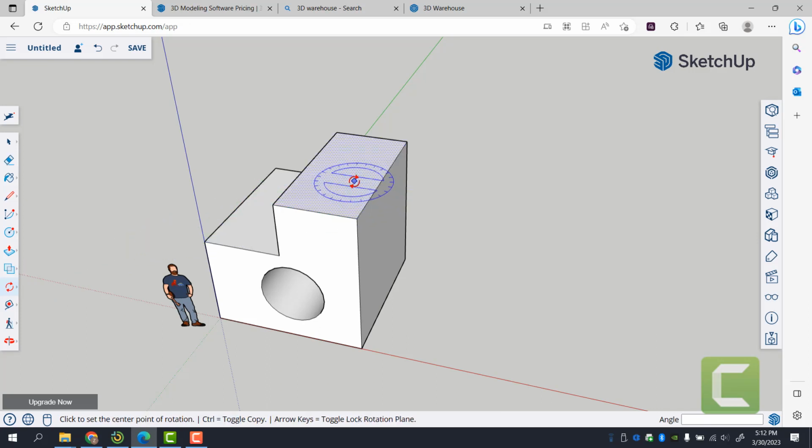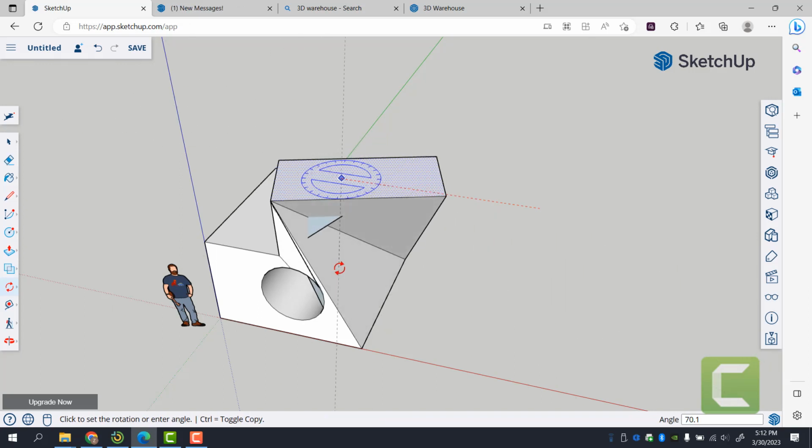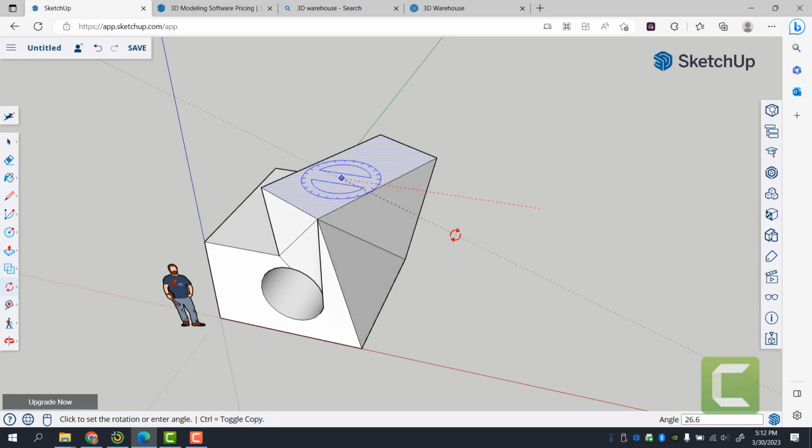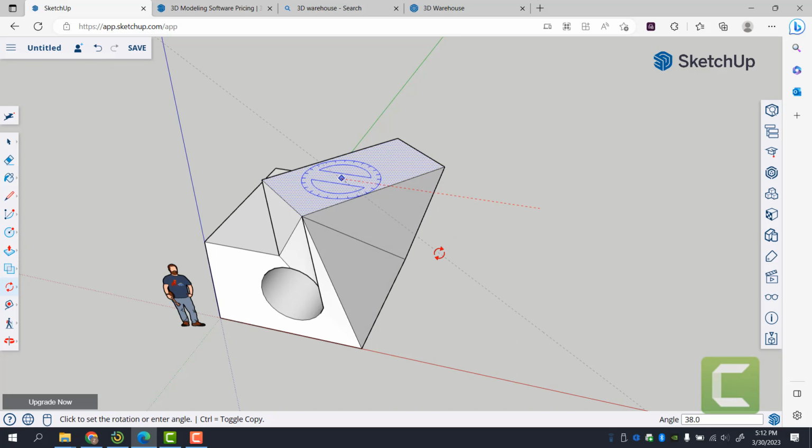And in the rotate tool, notice how I'm on the blue axis, which means there's a line going through that point on blue axis for reference of rotation or axis of rotation. And I am going to rotate about this red axis and turn towards green. Since I have not selected the whole object, it's just turning that surface. Again, very easy to visualize how it's turning just that surface and trying to maintain the bottom base.